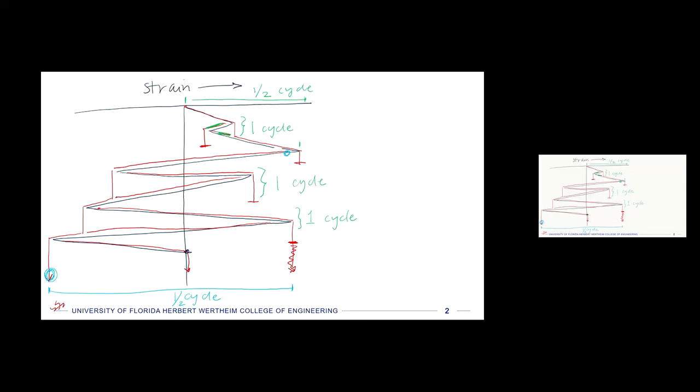And so then we've done all of our rainflows except for this last one here, which is just the half here. So we've accounted for all of the flow lines that we put in. If we add all of these together, granted these are at different amplitudes, we get 1, 2, 3, 4.5, I think. Yeah, so we get 4.5 cycles of stress here.